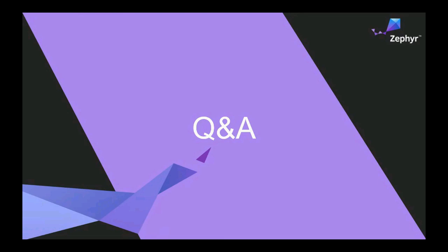Just another one for Lucas, using SPI and I2C on nRF52, whether you use the Zephyr API or the NRFX libraries directly, since NRFX is included with Zephyr, that's up to you. Both have advantages and disadvantages. If you use the Zephyr API, it's probably simpler, and you can then switch or port your application to another chip in a much easier way. You don't need to change APIs. NRFX will give you finer grained control over the hardware. So that's really up to you and your application.